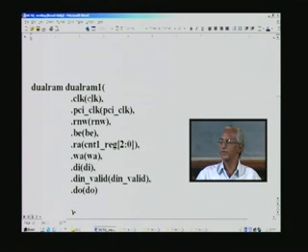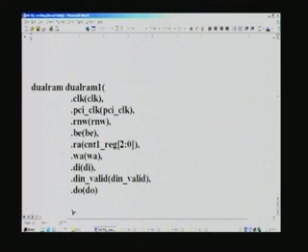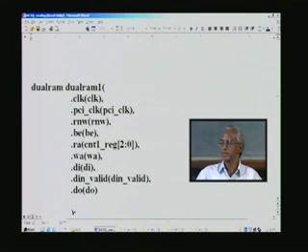and these are all the signals that you are already familiar with, and the only difference here is that in dual RAM we basically have two modes. We can either be in read only mode or write only mode. To start with, it will be in write only mode, and this R and W signal is what is being used for that, and while in read mode, we execute the DCT queue, and this read address will be delivered from the controller, by using a counter, and the same counter is also used for the ROM later on, the ROM for C and CT matrices.